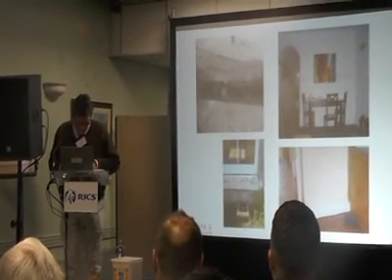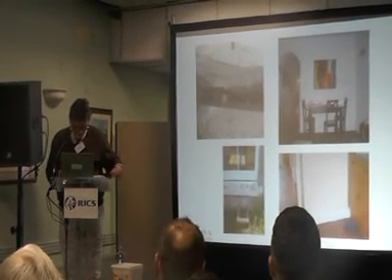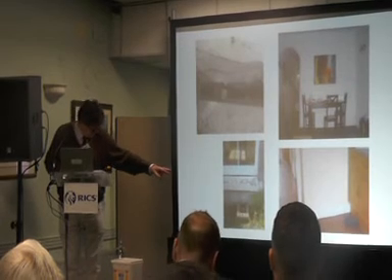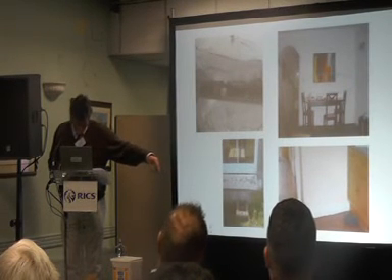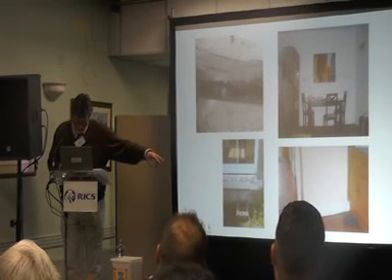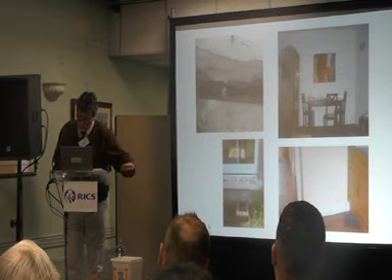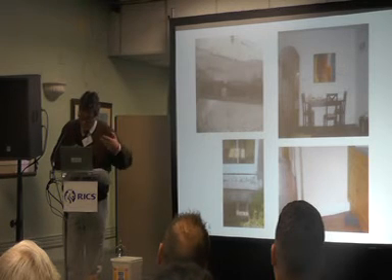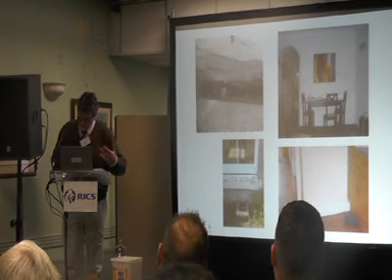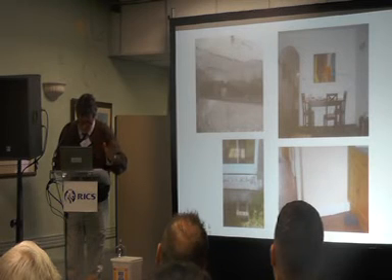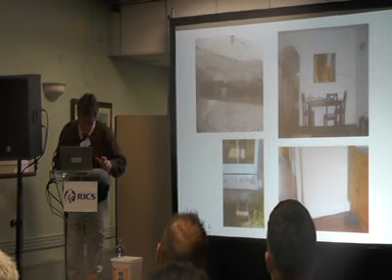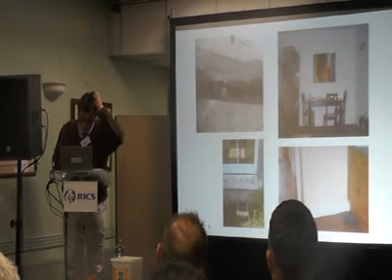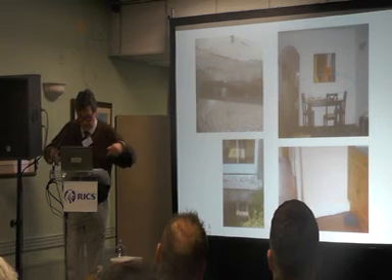The same house to the right, this is an internal masonry wall in a kitchen, bottom right there. We've got an internal wall just sopping up moisture from under the building. Now in that case what we did is we took the floors out of the building. This is extreme, but anyway, we took the floors out of the building and we put a whole series of perforated drains